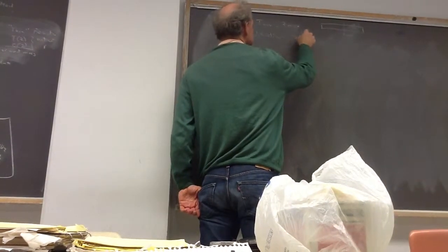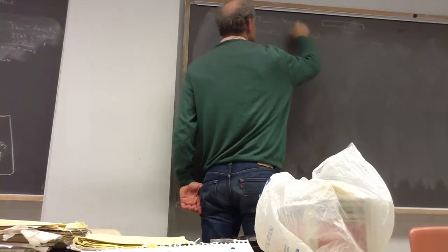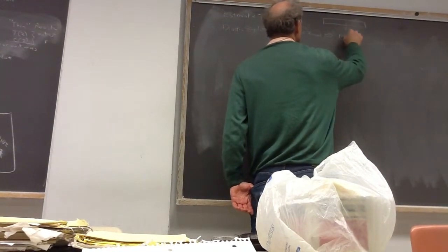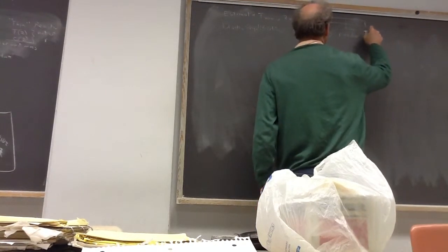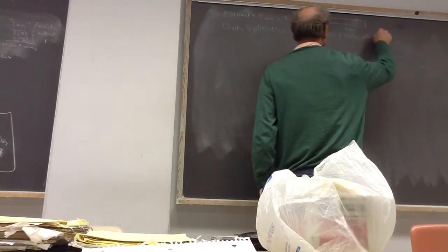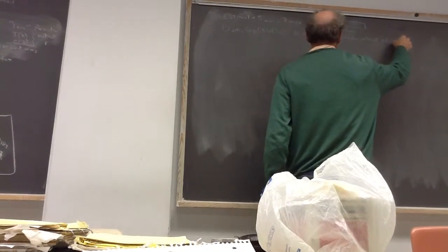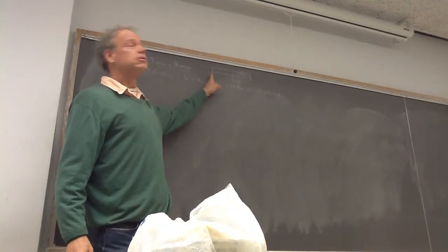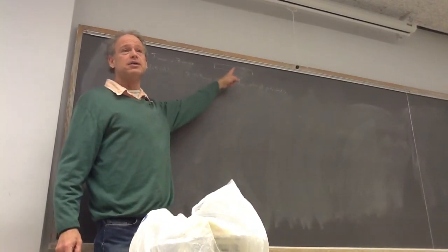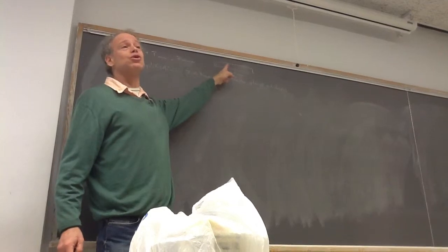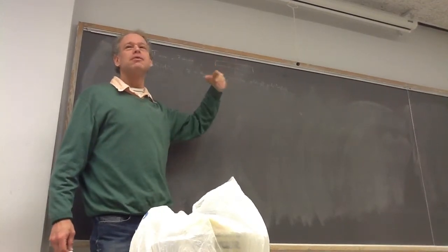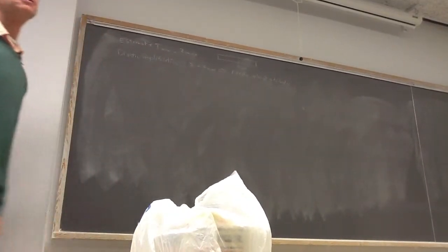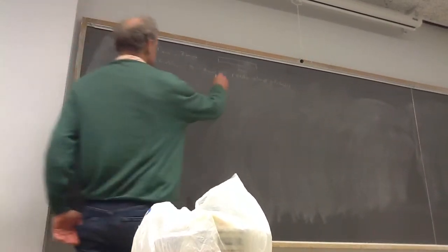That Z less than Z max, until I get to Z max, implies the reactor is almost adiabatic. That's certainly true near Z equal to 0. It's not true near Z equal to Z max, and the closer I get to Z max, the worse it is. But we're making simplifications here. Okay, that's for the first part of the reactor, this part.